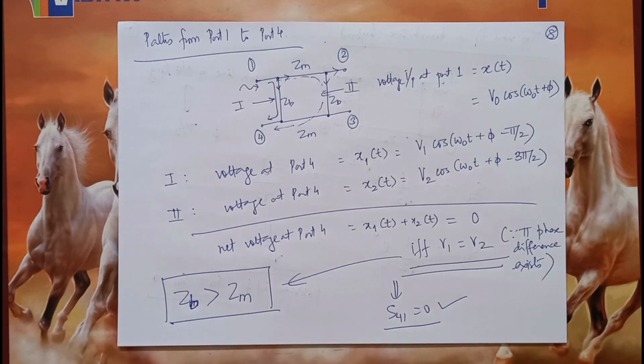So in today's lecture, we discussed some drawbacks and some interesting properties, and thereafter the drawbacks of coupled line directional couplers. Their major drawback is that they are essentially loosely coupled lines, and that motivated us to go for the structure called hybrids, where we can achieve higher values of coupling.